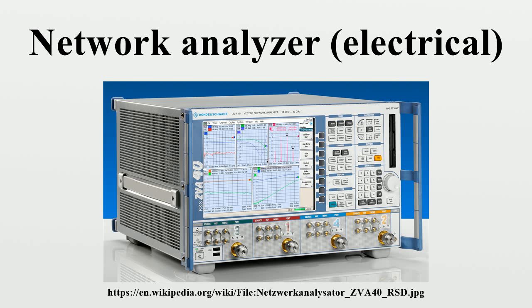A network analyzer has connectors on its front panel, but the measurements are seldom made at the front panel. Usually some test cables will connect from the front panel to the device under test. The length of those cables will introduce a time delay and corresponding phase shift. The cables will also introduce some attenuation. The same is true for cables and couplers inside the network analyzer. All these factors will change with temperature.